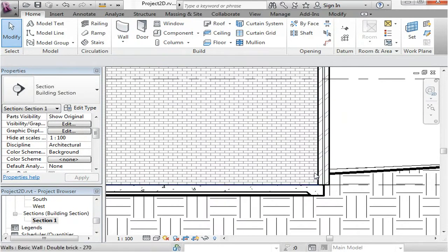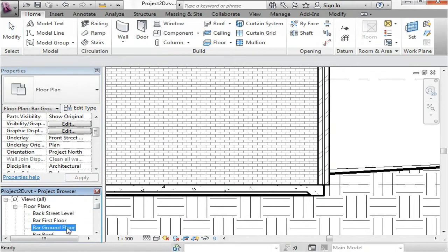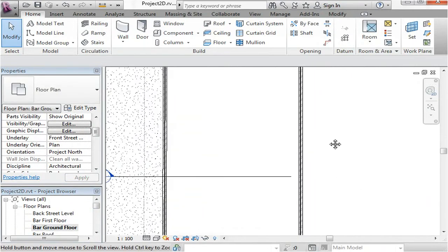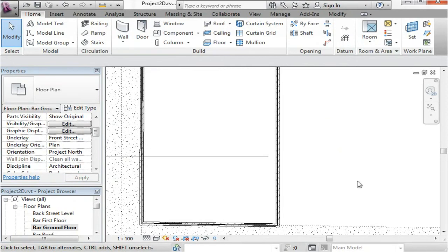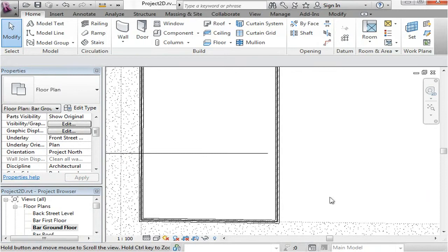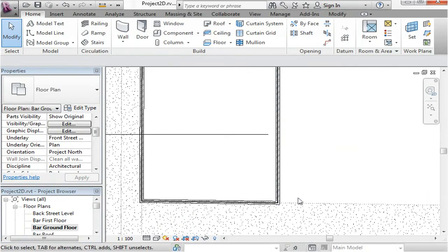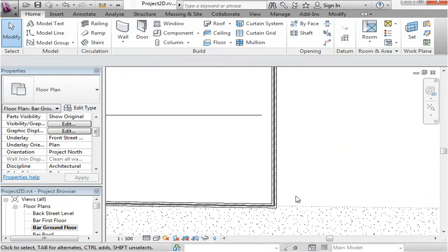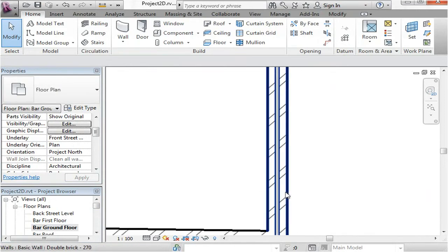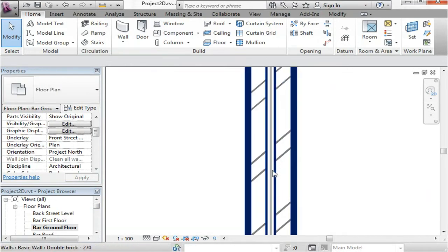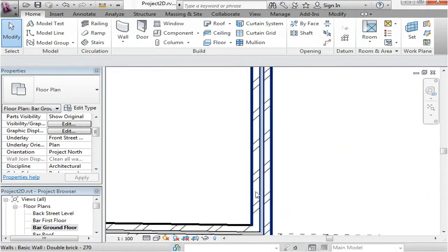Okay, so it's actually stopped at the roof level for me. Now we need to fix up this thing. So let's go back into the ground floor. Now the reason why that happened was the setting for the wall that we created was set on center line. In other words, the center line of the wall will be aligned to the line of the profile of the wall, so how I actually draw the wall. Now we can change that, but we do need to see the center line of the slab, and you can see that slightly underneath there, so it's just a gray line.